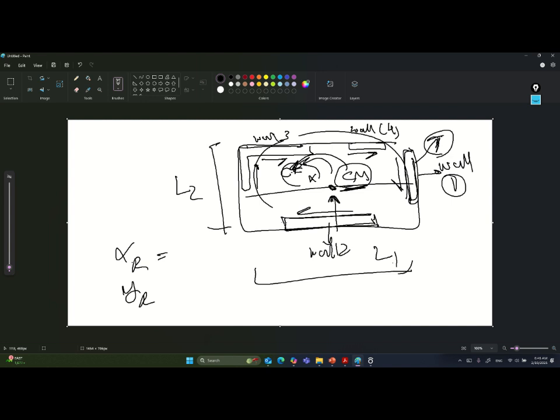Okay, so that is the resisting force, and the base shear is coming from this way. Also the walls in the direction parallel to it will also act this way. So I consider the inherent torsion and consider the actual force coming from here, which is acting on this wall.